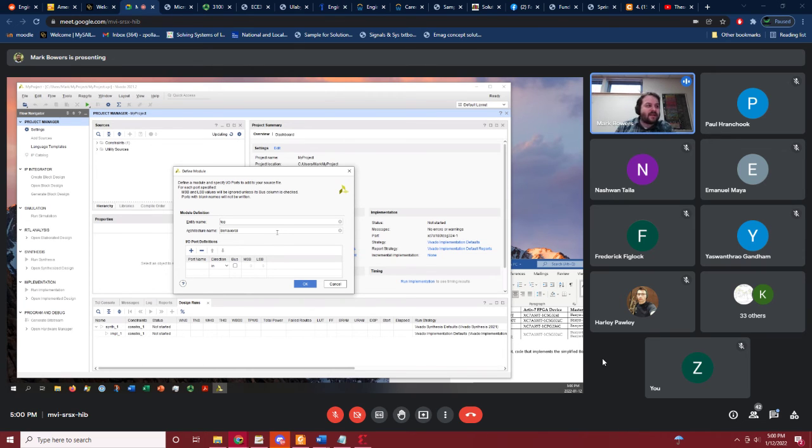Okay, for a lot of these we're going to code from scratch pretty much, but it has a little thing here that you can use to make a template for your top level file really quickly. So we're going to just have 2 ports in this file. We're going to have switches coming in, in lowercase. I'll show you why in a second. And that'll be a bus, just a 1-bit bus. And then we'll have an LED going out, and just another 1-bit bus.